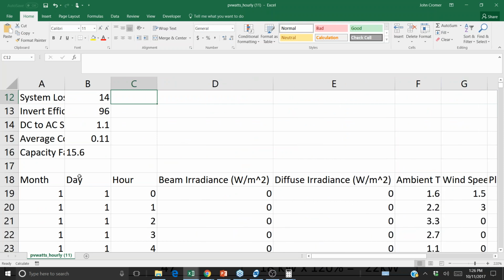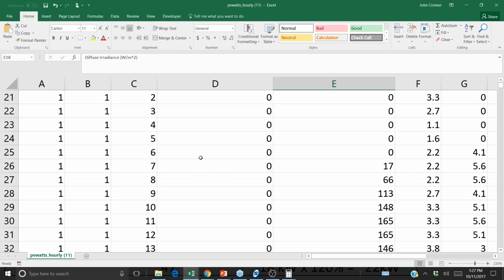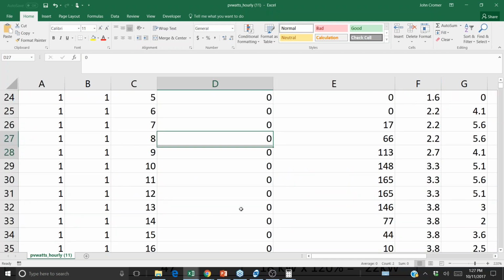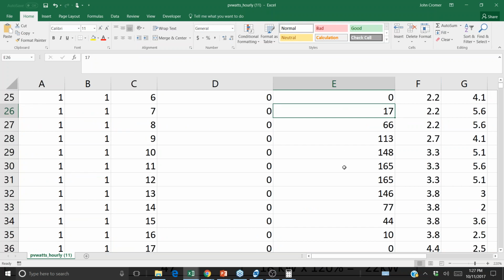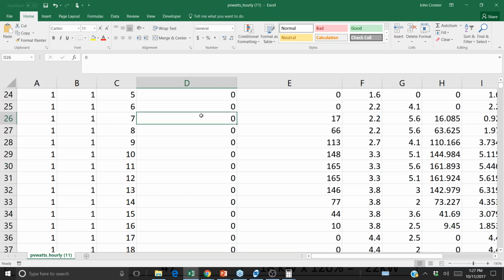it's taking hourly weather monitoring data from that weather monitoring station and says, okay, well, we know how much sunlight was in the air at the time. Let's check the weather conditions and convert it into direct irradiance versus diffuse irradiance. And so on January 1st, we see that we have no direct irradiance and we only have diffuse irradiance. And so on January 1st in Starkville, Mississippi, this is a completely overcast day where you have a big, thick gray cloud sitting on top of the array.